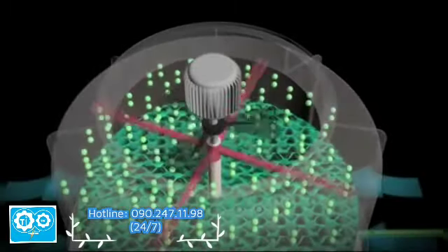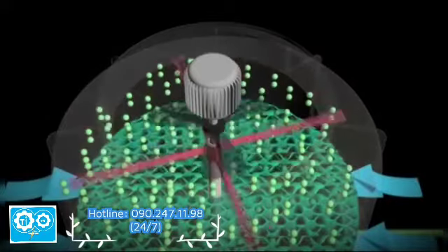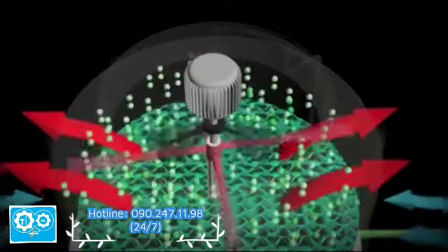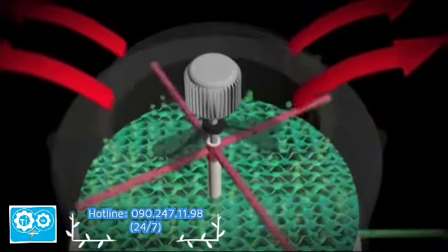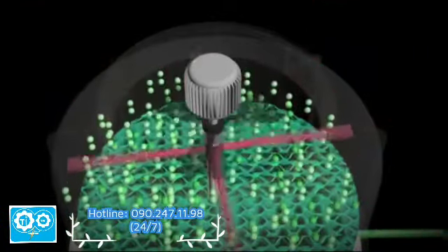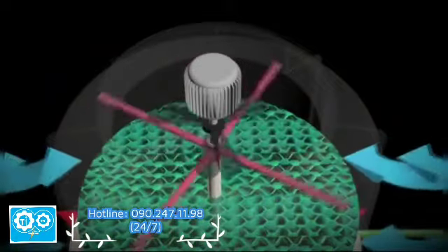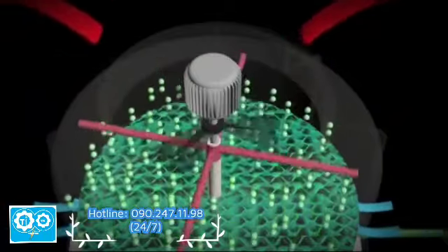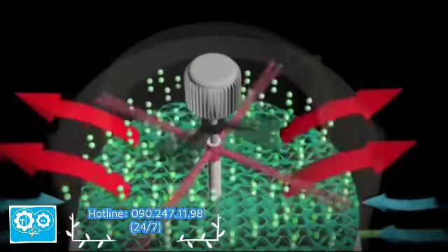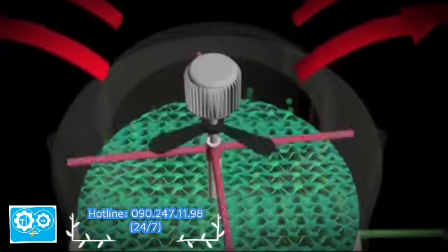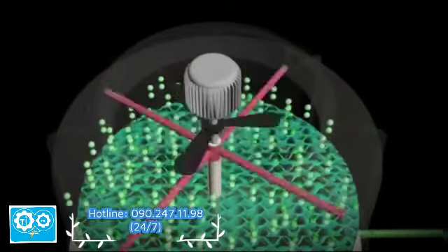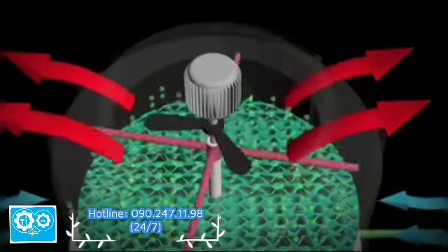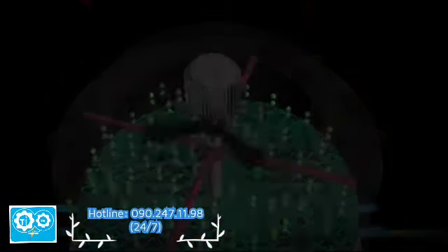Water will gush down through the fins to reduce the speed of water going down. This delays the time so the heat can be absorbed more effectively by the surrounding air passing through the fins. Air through the fins is forced by a rotating fan on the sprinkler blade rotated by the motor. This fan rotates with its gusts upward. This causes the air to move from the bottom to the top of the cooling tower, opposite to the flow of the condenser water.